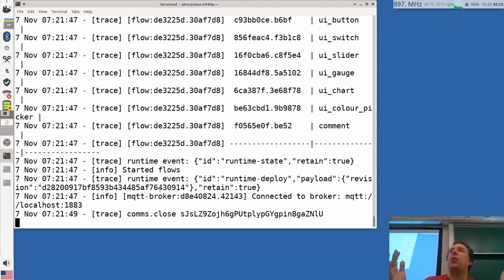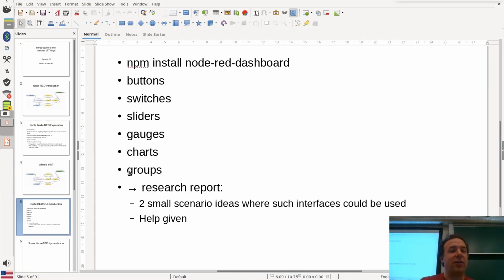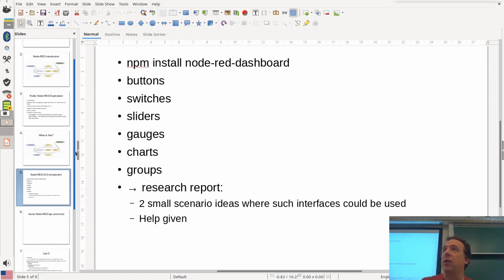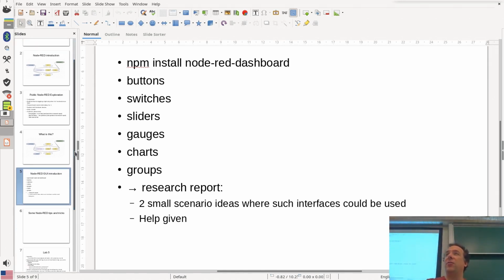I cannot install, so what I managed to do is to install Flogo on the Raspberry Pi as the command line version. So you can install Flogo command line, and then you can put JSON files in there and compile JSON files for the Pi on there. However, you cannot use the web UI on the Pi, because it only works on x86 systems. So there's one JavaScript library in the Flogo web UI, a lot of JavaScript part that doesn't work on ARM architectures. That took me 2 hours to figure out.